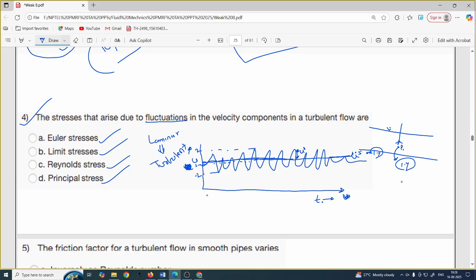You already know that in the flow we actually have three-dimensional flow. One is streamwise, that is longitudinal, then lateral flow and vertical flow. Similarly you will get corresponding u fluctuation, v fluctuation and w fluctuation. Based on these three fluctuation components, we get the Reynolds shear stress, which has 9 components: u dash u dash, u dash v dash and u dash w dash.